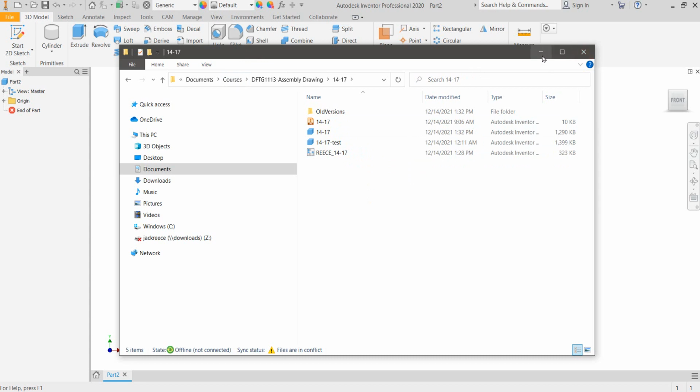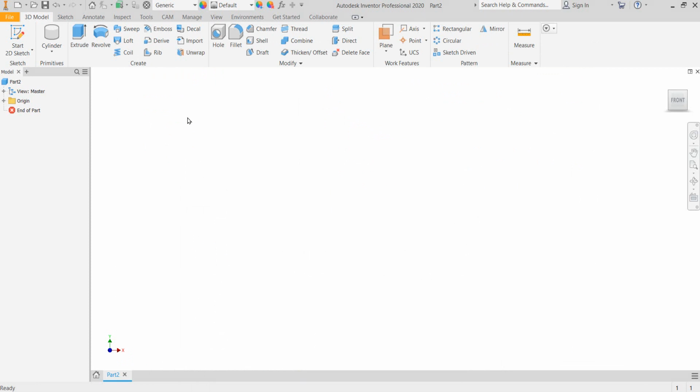Okay, so you can either create a folder using the File Explorer or in Inventor when you go to create a new project. And you do that before you start a part drawing. Up here you click on Projects, create a new project, create a new folder, give it a unique name. The assignment number works good. I store mine in folders by weeks, so I know what they are, because I have to reference back to them quite often. Anyway, everything works off of projects in Inventor.